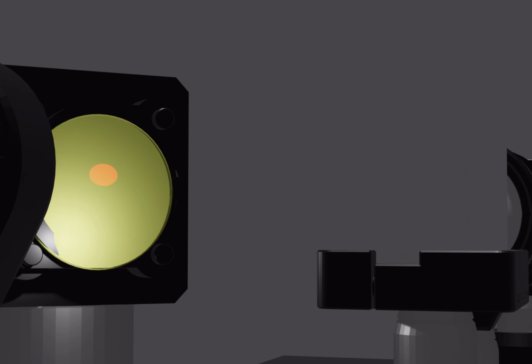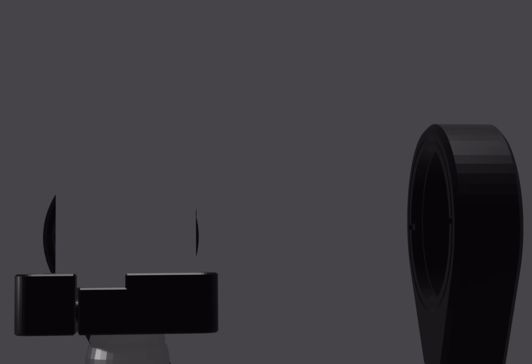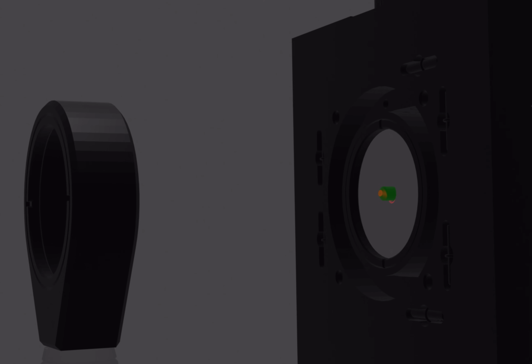With beam steering enabled, the fast steering mirror is capable of reducing the error significantly and directs the beam onto the optical fiber, which is 10 microns in diameter, with minimal error, resulting in a greater than 90% power retention.